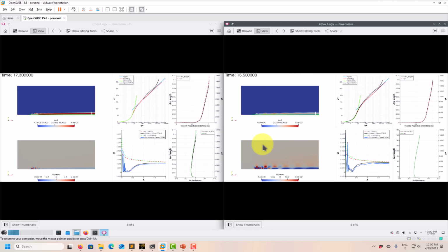Now the K omega SST, look at that, it's not dissipating the behavior. You have it there, you have your turbulent viscosity, all the fluctuations, everything you see here. The wall modeling, this is what I was expecting, contrary to the other case, that here you are going to see those fluctuations, but there everything will be damped or erased or diffused from your solution. You don't see any fluctuation there, very small. Instead here, look at that, this is still dancing. Okay, so this is our K omega SST.